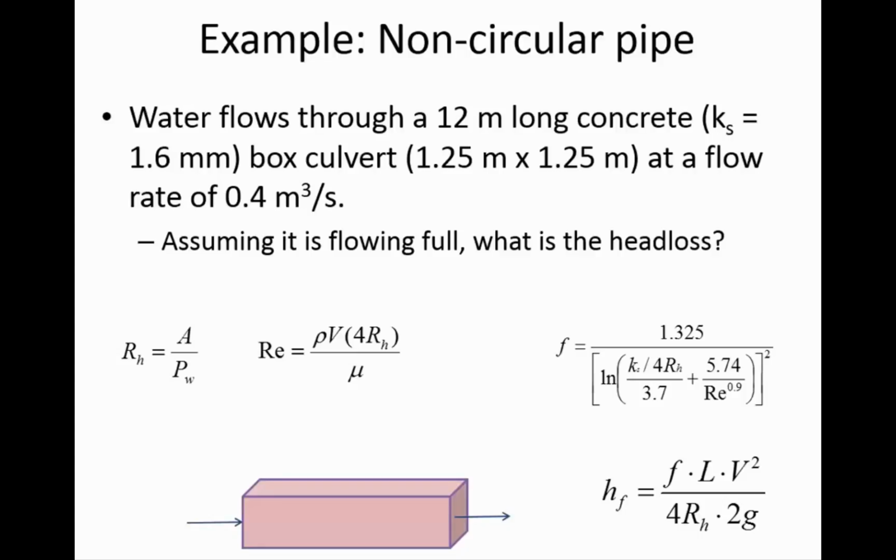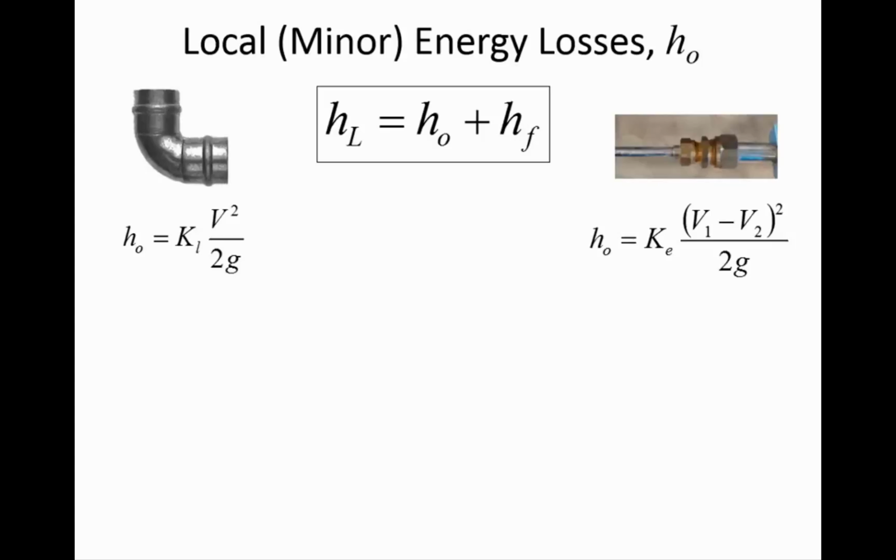All right. Well, let's talk about local losses then. And remember, I previously have said that the pejorative term for local losses is minor losses, and we don't use that term because it implies that the losses aren't important. And usually that's true. But there are really important cases where, if you neglect the local losses, you're going to get a really bad estimation of what the pressure is, or of how much loss has occurred from one place to another.